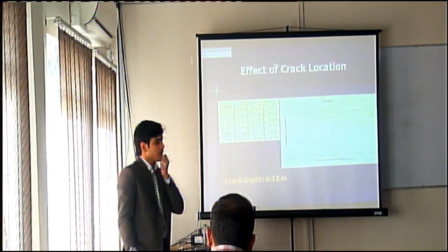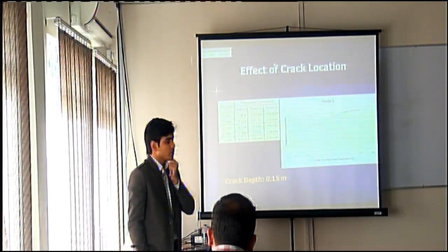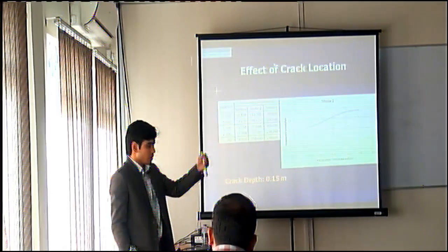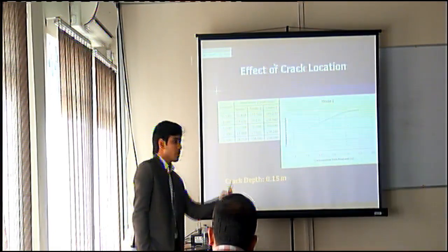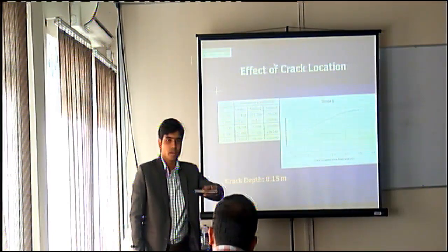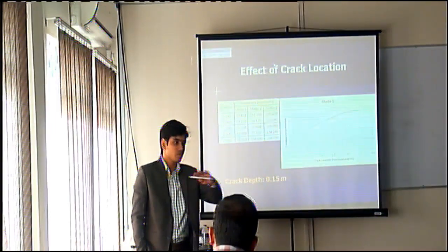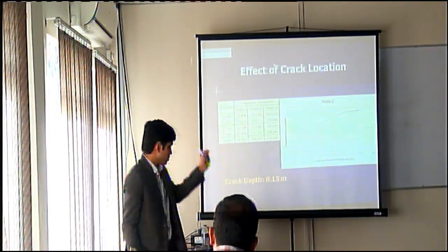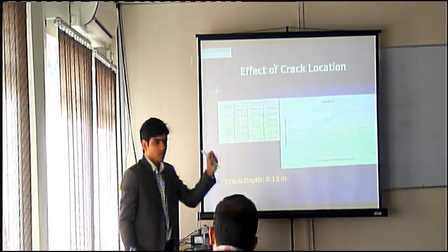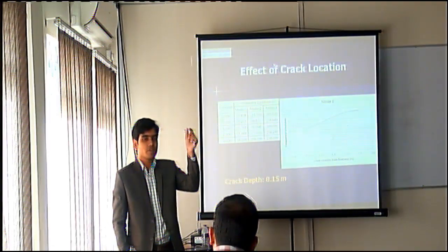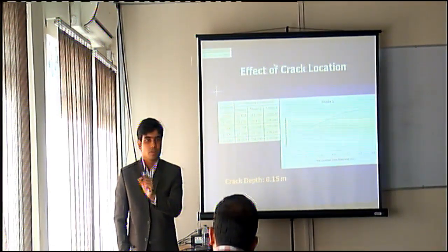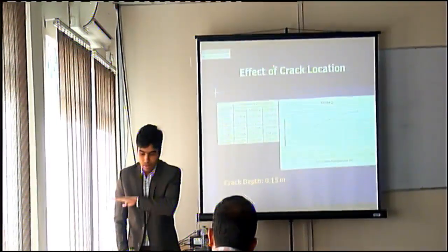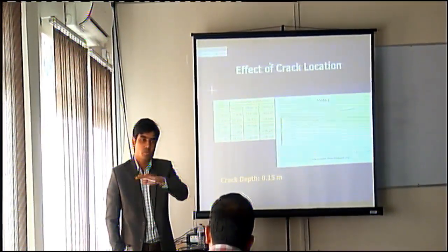And I can add here that in the software there is extended FEM. There is an option where you can just draw a line or plane and it can act as a crack. So you don't need to specify a notch with an opening of some millimeters. You just draw a plane and it will act as a crack.